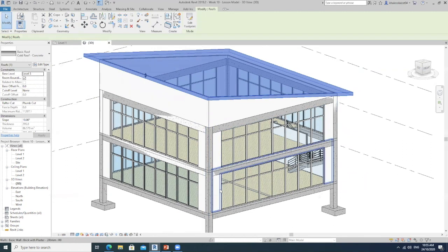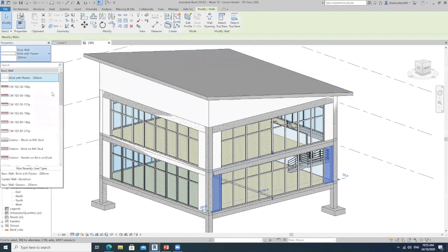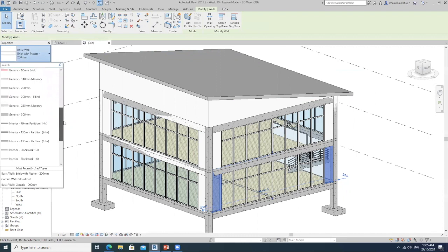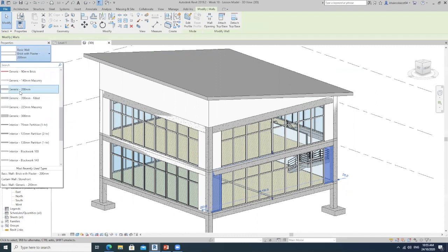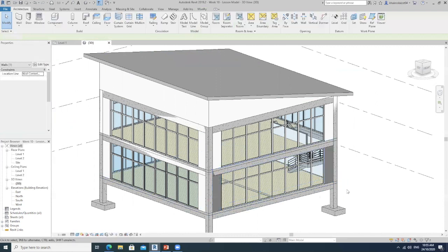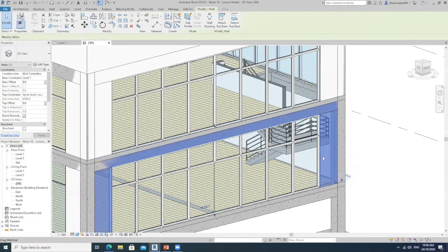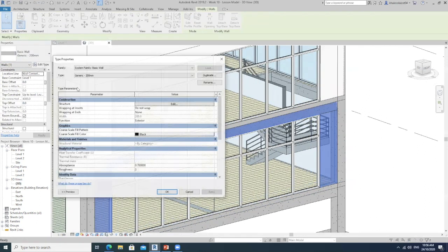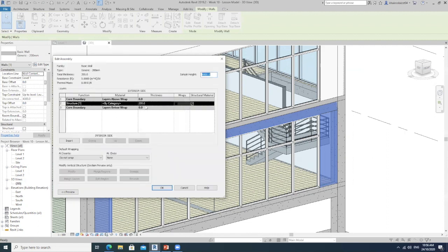Unless your wall, or perhaps any elements within your wall, is using generic materials. Like for instance this part, this is a generic wall. If you edit type, then you will not be able to see the analytical properties because there's no material associated to the generic wall yet. This is just conceptual. So notice no material has been applied, therefore no thermal information for that particular material.